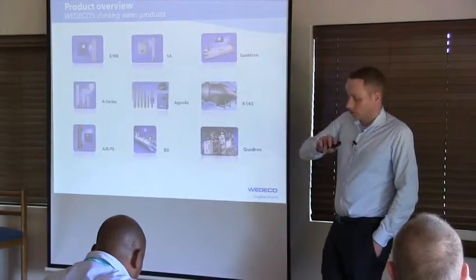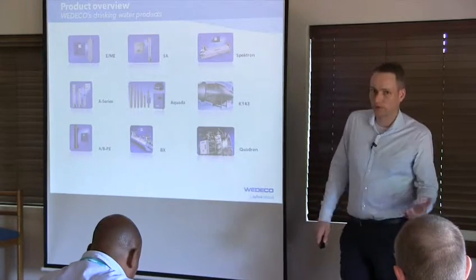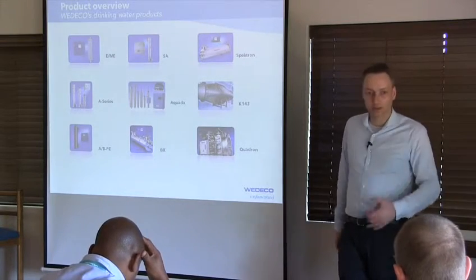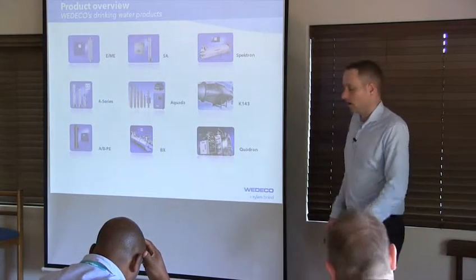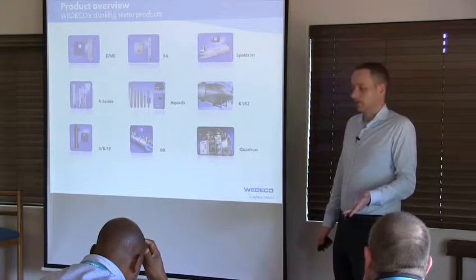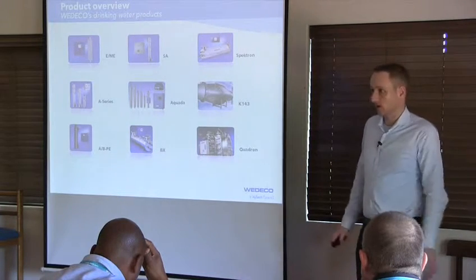but up to a certain amount of iron, the only effect you have with iron is an increased fouling potential on your quartz sleeves, but that is something which the wiping system can take care of. So you have to look at a case-by-case basis how high your iron concentration is.